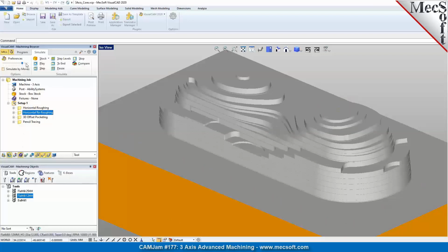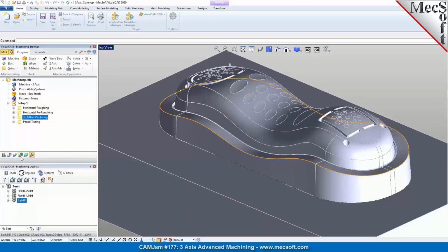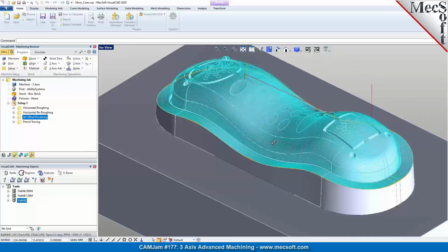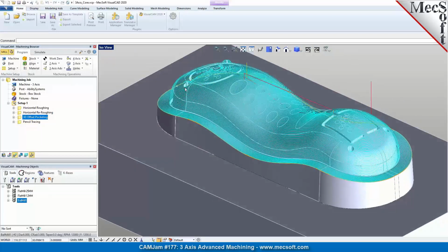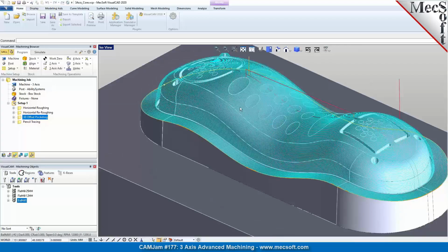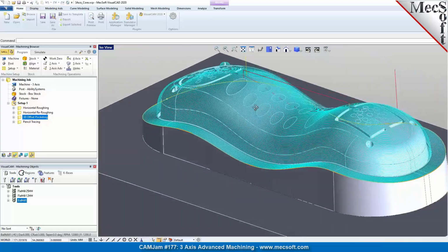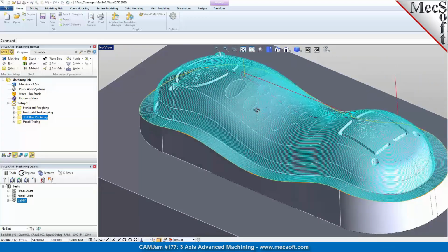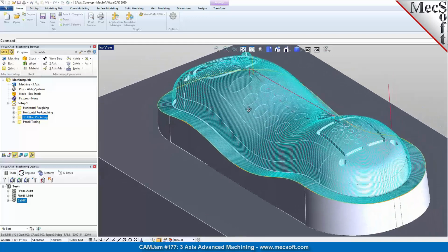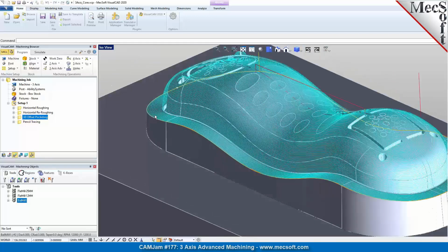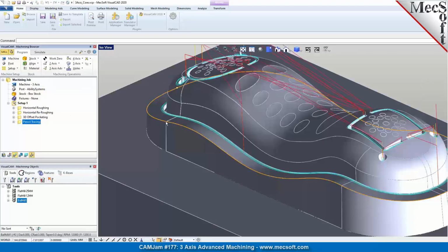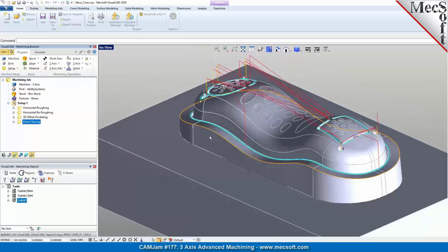And then you have your finishing toolpaths, which could be a 3D offset pocketing, which creates a constant 3D stepover or uniform stepover. So this can be used for both mold cores and cavities, the 3D offset pocketing method. And you could apply a cleanup pass to go back and identify those bitangencies to clean it up using a pencil tracing toolpath to clean those areas out.